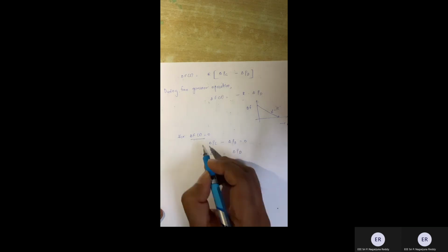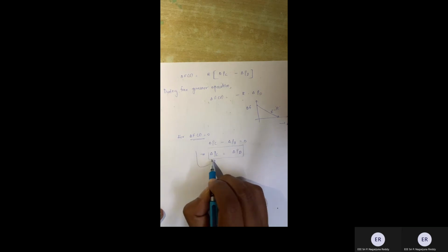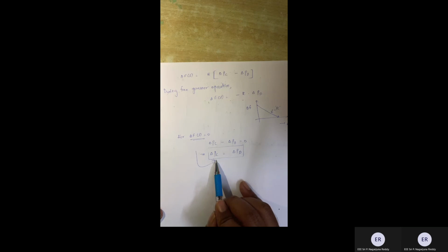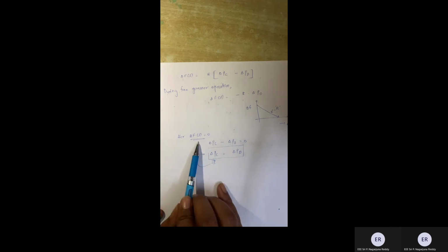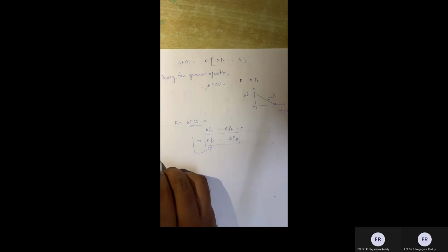This is the condition which I am supposed to maintain. Whatever the demand change is, I must manually change the speed changer setting so that the generation has increased. So this rule is to be followed if you want no change in the frequency. Now, having said that, moving on to dynamic response.